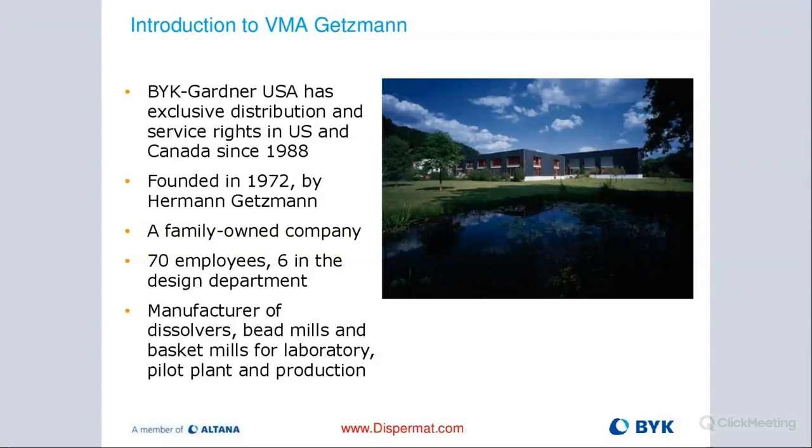They make a really good quality product. One of the big differentiators, I have to say, is their motor technology. All the motors built in Germany that VMA uses for the dissolvers or dispermats are brushless direct drive motors. If you have ever worked with a high-speed mixer, you would know the advantages. They're super quiet, they have hardly any vibration, and they will last a very long time. Basically, no maintenance is needed, and the shaft goes right into the motor, so there are no belts to be replaced or anything greased. It's really very good, solid technology.